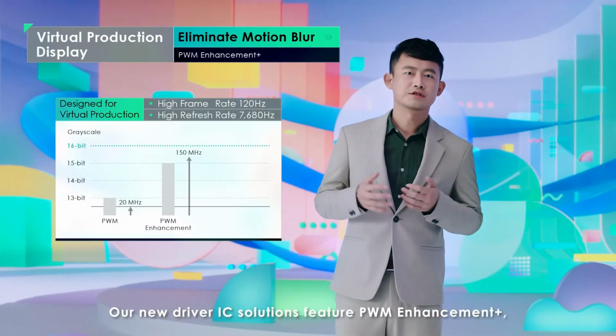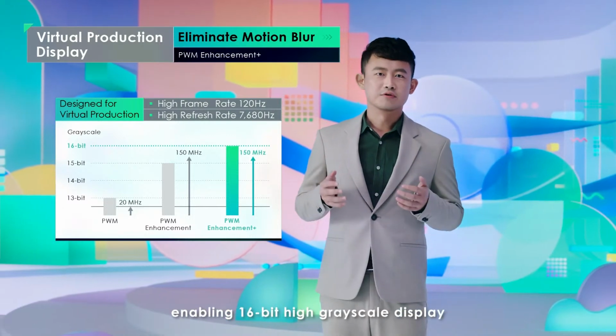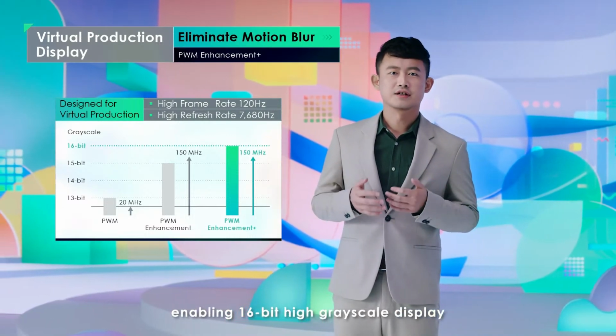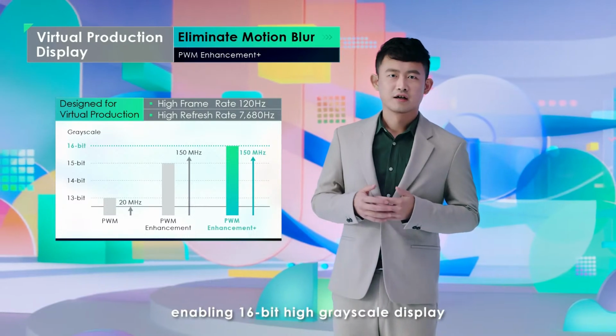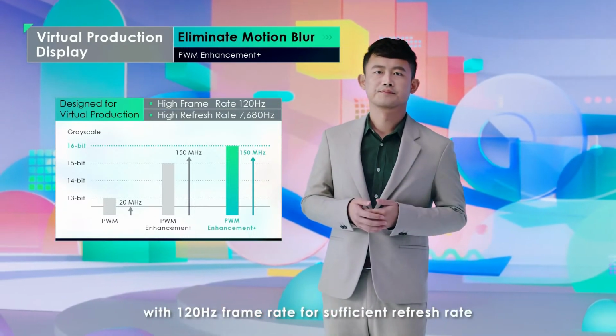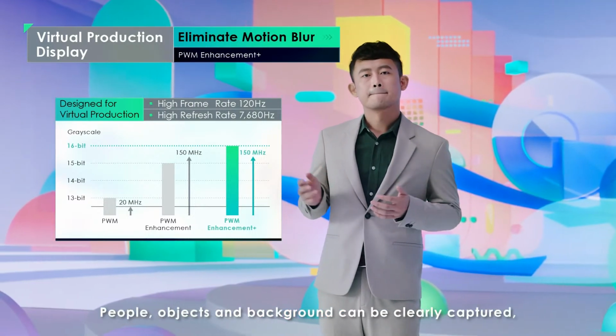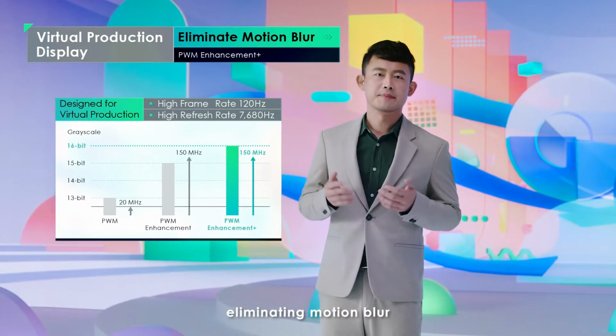Our new driver IC solutions feature PWM Enhancement Plus, enabling 16-bit high grayscale display with 120 Hz frame rate for sufficient refresh rate. People, objects, and background can be clearly captured, eliminating motion blur.